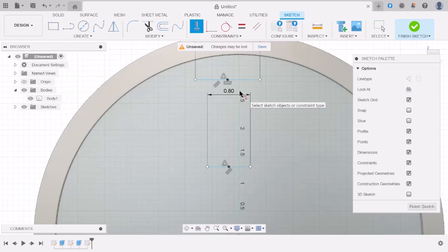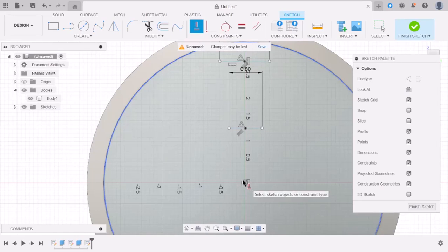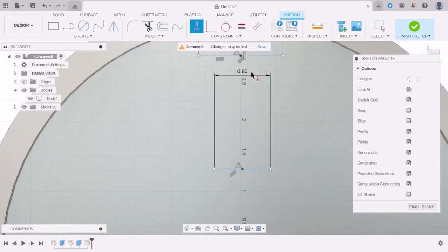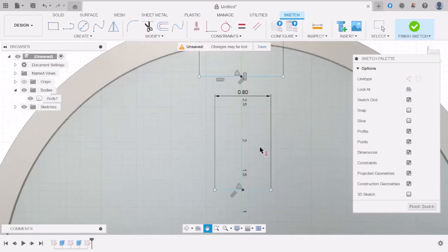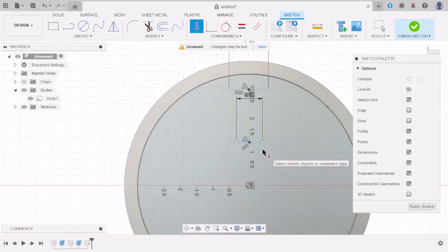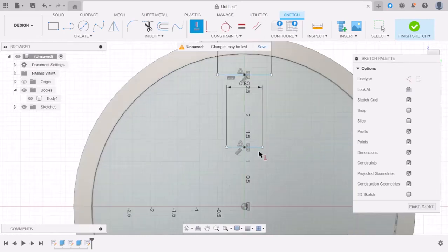Now if I click this center here and I click here, you'd see it would align it back to this center, and it gives me another symbol here telling me that this center point now is on the same point as this center vertex here. This center vertex marks more or less the center of our plane, and we can repeat the same thing here. See, now this is equal, but what's not equal is